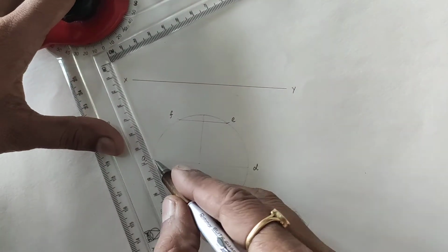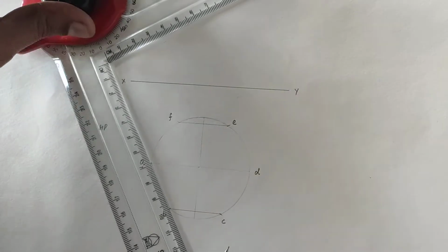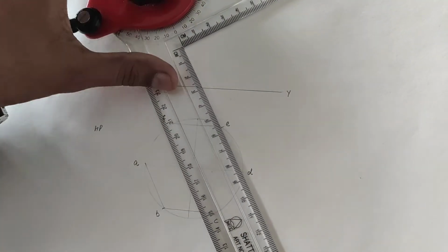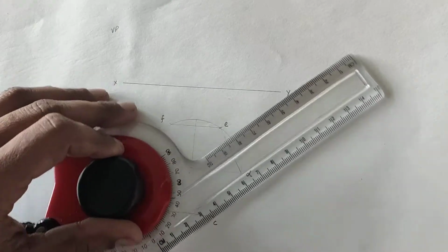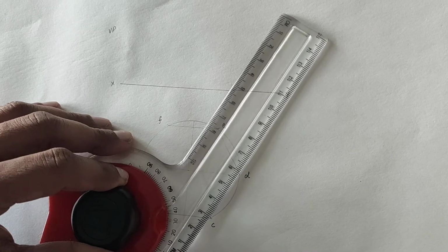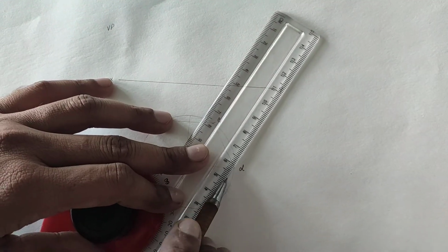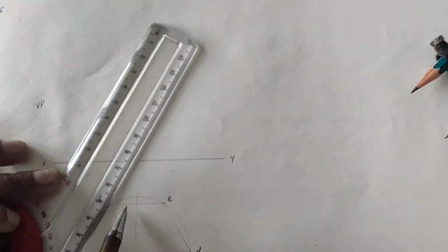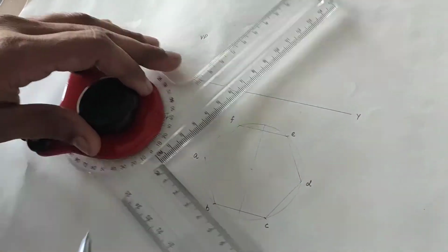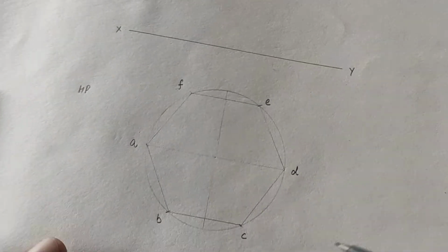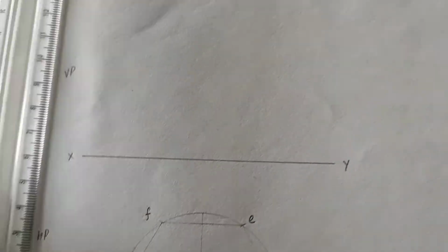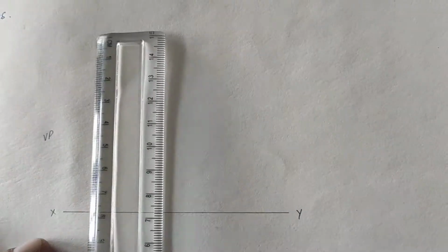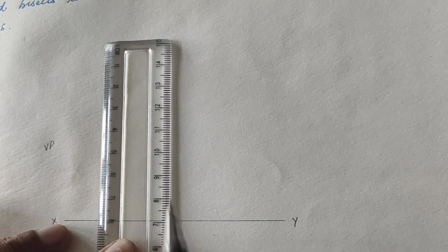Why are we making it with a continuous thin line? Actually, this is a problem of section of solid, and we only mark it dark after we pass the section plane. So draw the hexagon. Okay, this is the center of the hexagon. Mark it O. Again align your drafter with the reference line and extend the center